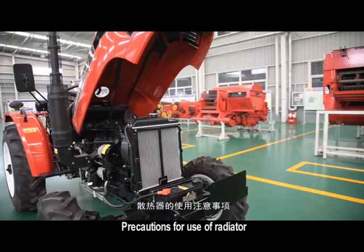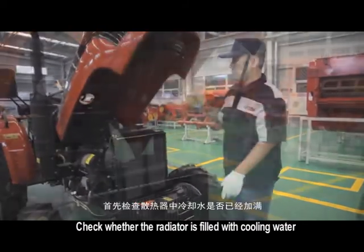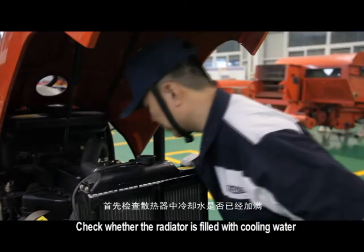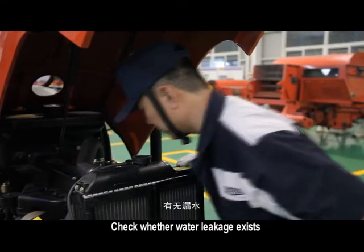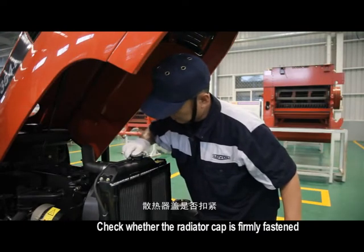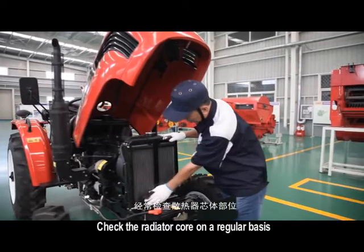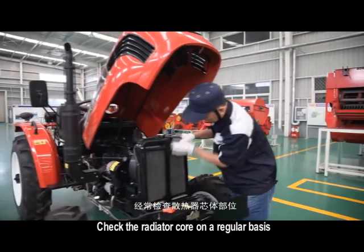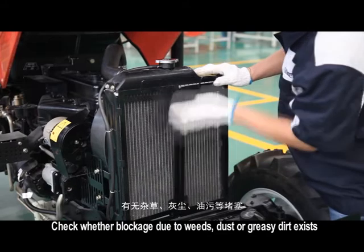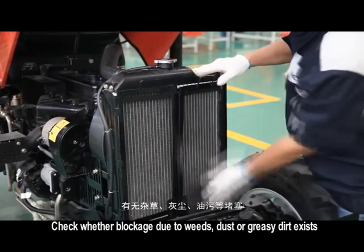Precautions for use of radiator. Before using, check whether the radiator is filled with cooling water. Check whether water leakage exists. Check whether the radiator cap is firmly fastened. Check the radiator core on a regular basis. Check whether blockage due to weeds, dust, or greasy dirt exists.